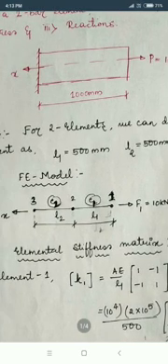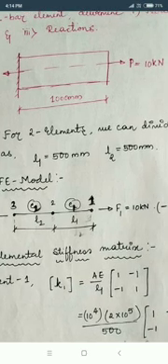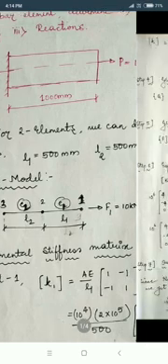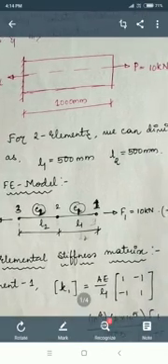At the extreme left end, you can see that there is a small arrow mark with X that indicates the left side direction is the assumed positive direction. The force which is acting opposite to this has to be taken as negative. That is, load P acting opposite to this X direction has to be taken as negative 10 kilonewton.